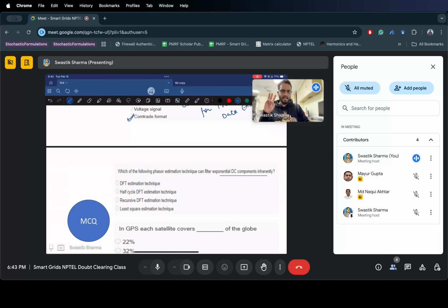For example, there are three standards we have covered up until now. One is IEEE 1547, which talks about interconnection of DRs to the distribution system. The other is IEC 61850, which talks about substation automation. And then your standards related to IRIG-B, for example, which talks about the GPS signal and time synchronization of the GPS clock.